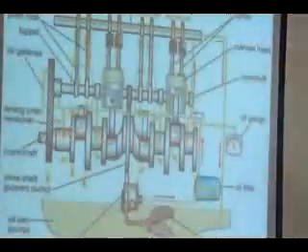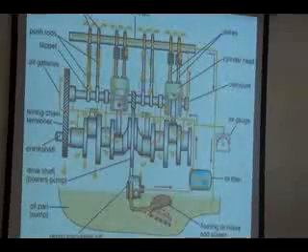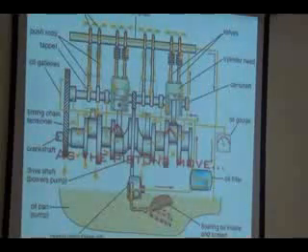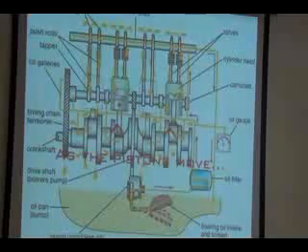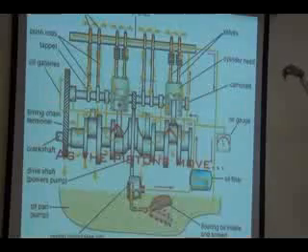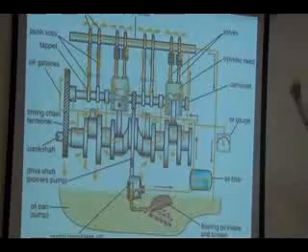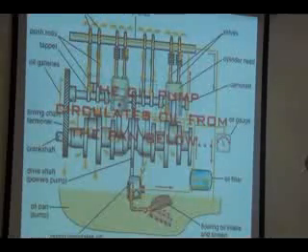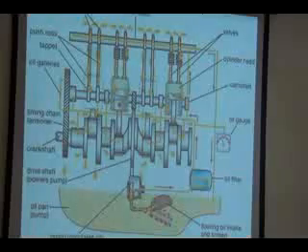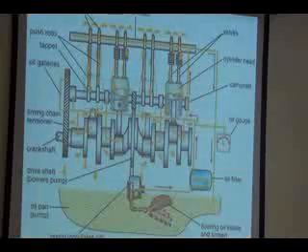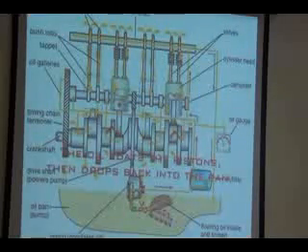So then lubrication system. There is a lot of relative motion taking place. Many places require lubrication. You have bearings, you have piston and cylinder, and you have all the journals. And you have many rotating parts, and reciprocating parts, valves are reciprocating parts. You have many rotating and reciprocating parts which need to be lubricated. That is done by a separate lubrication system. There can be various types, like splash lubrication, and all that.